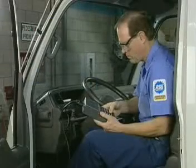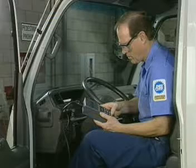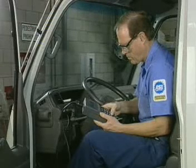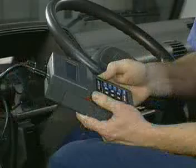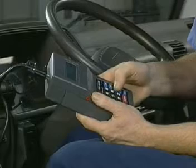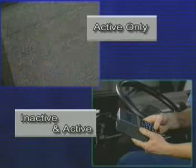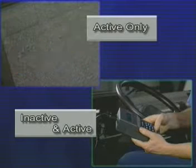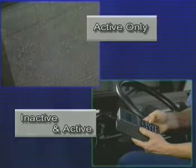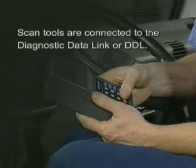On vehicles with electronically controlled engine management systems, check the onboard diagnostic system for any stored diagnostic trouble codes. The diagnostic trouble codes, or DTCs, can be retrieved using a scan tool or by retrieving the blink or flash codes. Scan tools will read both inactive and active codes, while the blink or flash codes will generally only show active codes. Scan tools are connected to the Diagnostic Data Link, or DDL.